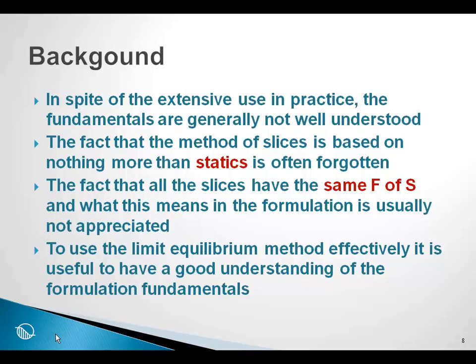Interestingly, in spite of the extensive use in practice, the fundamentals are generally not well understood. For example, the fact that the method of slices is based on nothing more than statics is often forgotten. Also, the fact that all of the slices have the same factor of safety and what this means in the formulation is usually not appreciated.